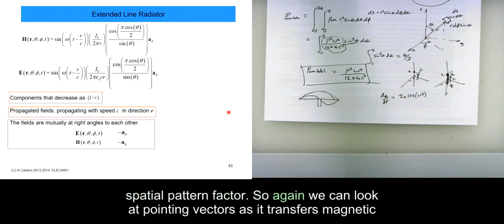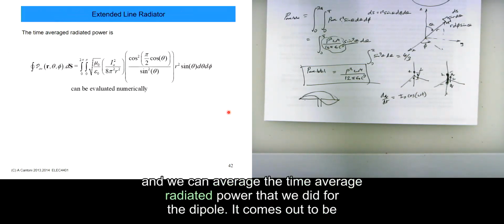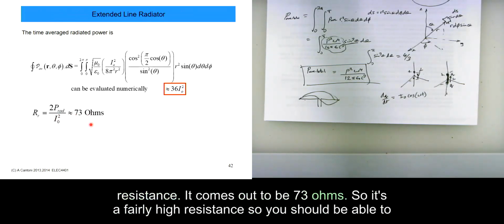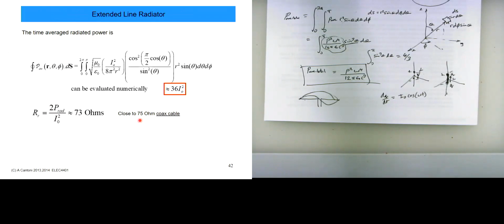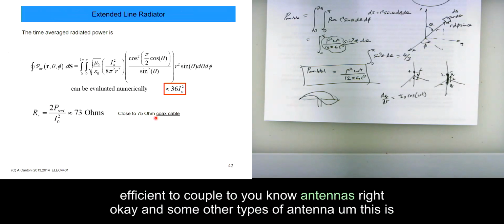So we can look at Poynting vectors as transverse magnetic, and we can average the time-averaged radiated power like we did for the dipole. It comes out to be 36 I naught squared. We can do that numerically, but we can equate that to a radiation resistance, and it comes out to be 73 ohms. So it's a fairly high resistance, so you should be able to deliver a lot of power to that and radiate efficiently. And that's close to 75 ohm coax cable, and that's why they chose 75 ohms for coaxial cable, right? Of course, that's efficient to couple to antennas.